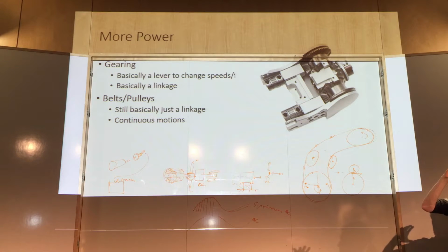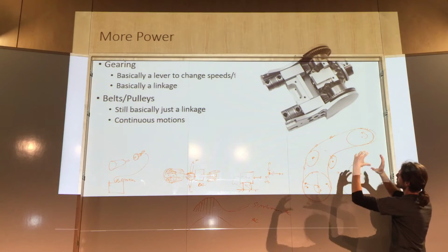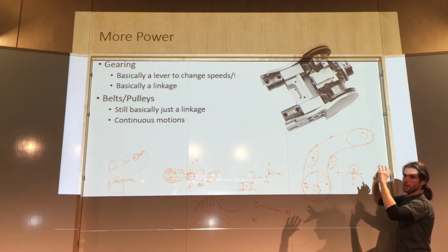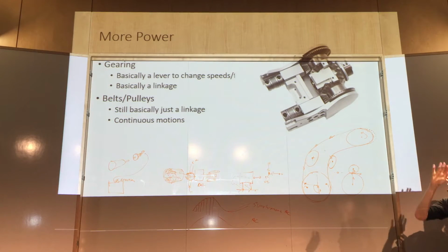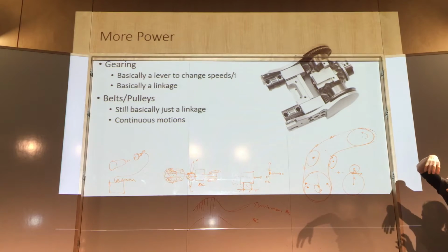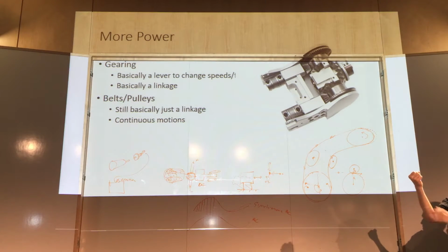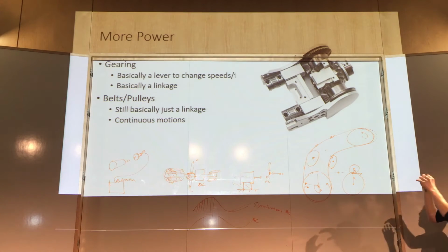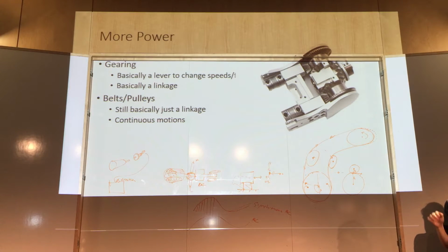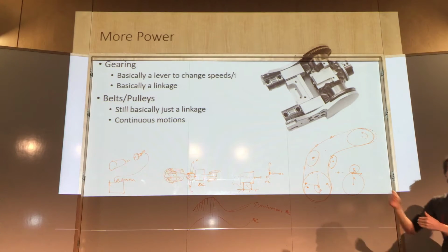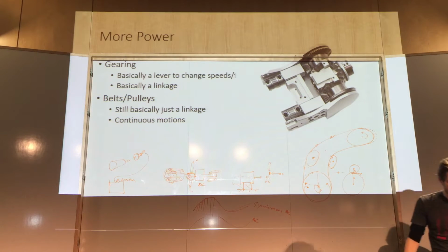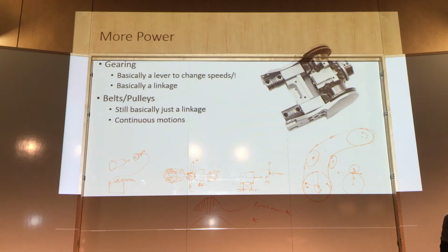You have 2 gears, and if you rotate them together, it locks up that gear on the output, and that gear just pitches forward and backwards. If you rotate them in opposite directions, it causes that gear to rotate, and so you get twist and pitch all from this one centered gearbox system. That's really nice when you have your axes aligned in the center, at the same point, because that's similar to what we do with our wrist. Rather than having a bunch of stacked joints that start stacking up and then your wrist gets really big and long.